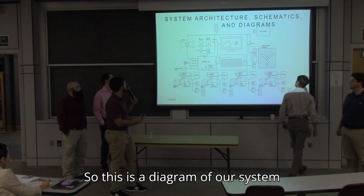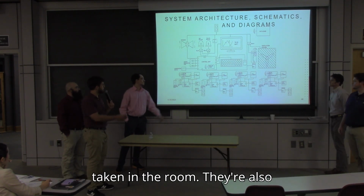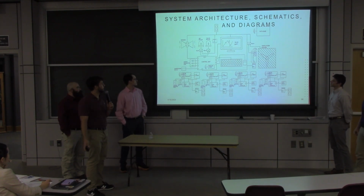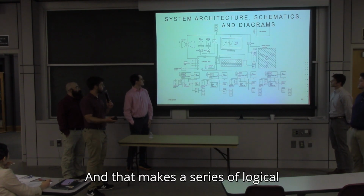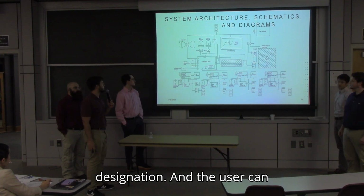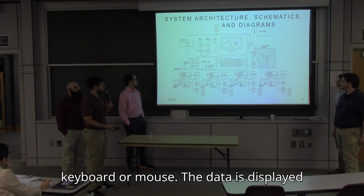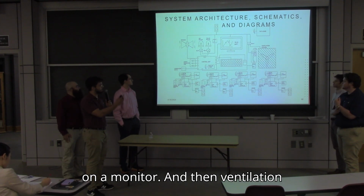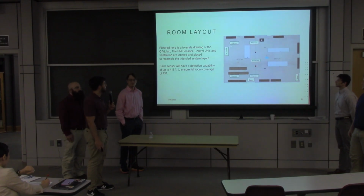So this is a diagram of our system architecture. At the bottom, you'll see our PM sensor modules. They read the data taken in the room. They're also connected to module power. And then those are sent wirelessly to the control unit you'll see in the middle. That makes a series of logical decisions based off the data, trips relays, sounds speakers, and handles the sensor designation. The user can interface with that control unit by keyboard and mouse. The data is displayed on a monitor. And then ventilation is also tripped according to the PM level.